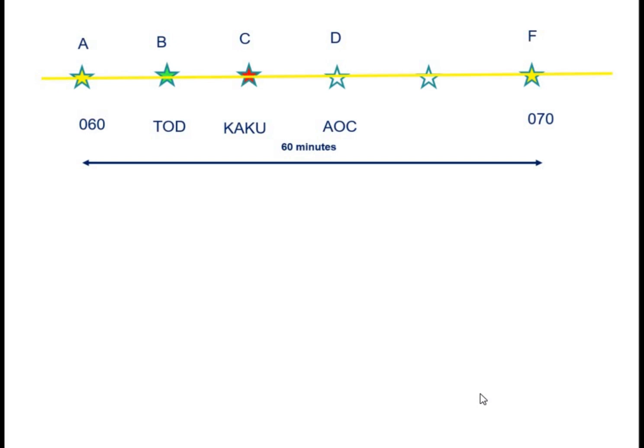Point D has been inserted by the pilot in the flight management system to trigger a report to the airline's operational control center. Point E is another ATS reporting point, CARDO. At this waypoint, no changes in speed or altitude are planned to occur.